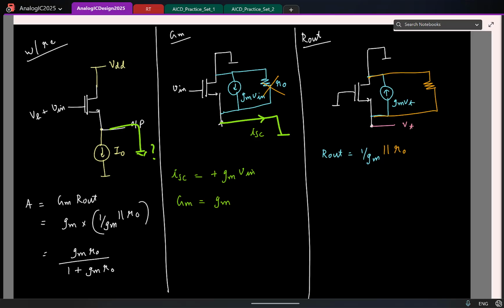Remember, I am basically finding the short circuit gm, but I am looking at small signal pictures here. So when I am short circuiting this, I am basically saying for small signals it's a short circuit. So if I have to actually go and measure this, what will I connect this to? You put a voltage source of that same operating point value.